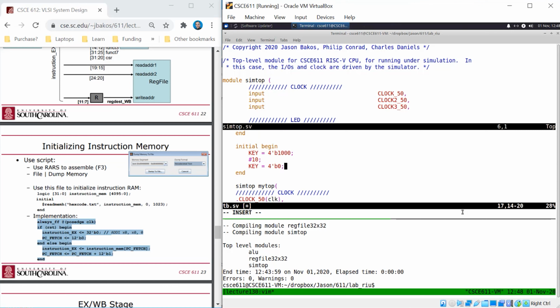That will drive our clock and our reset, and we need a simulated switch, so I'll just assign switch to be a value. Now, I forgot to change the load immediate inside my code for loading the switch value, so I'll have to remember to do that, but I'll leave this the way it is for now.